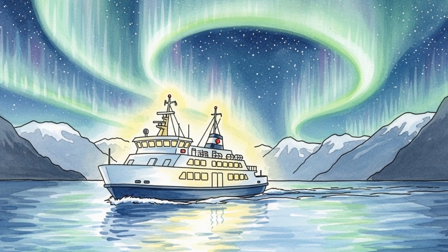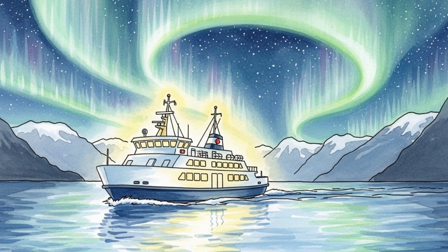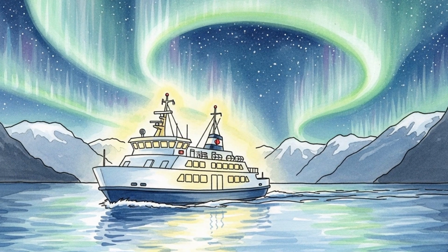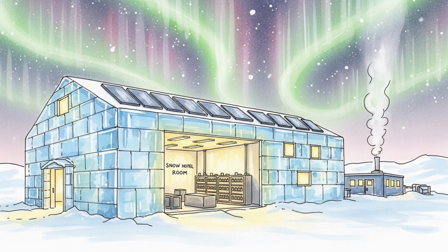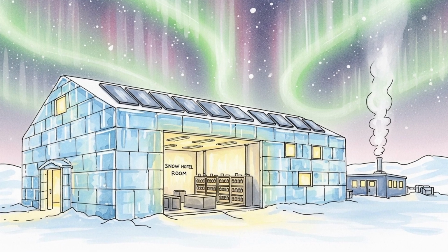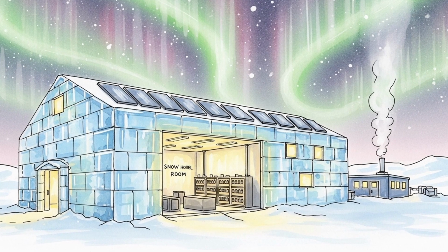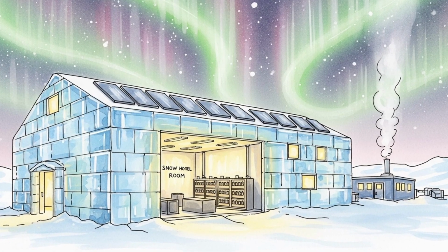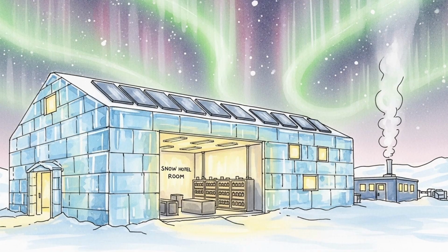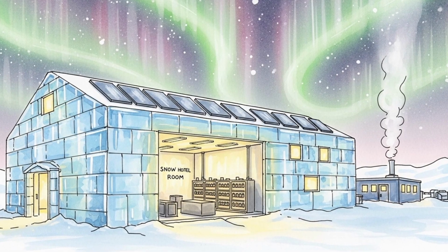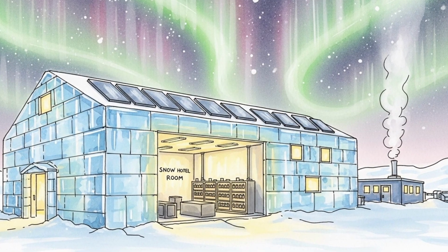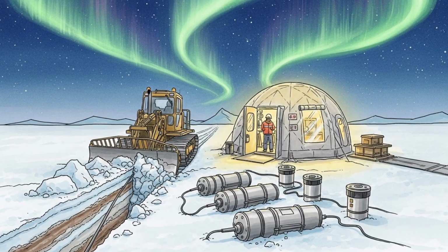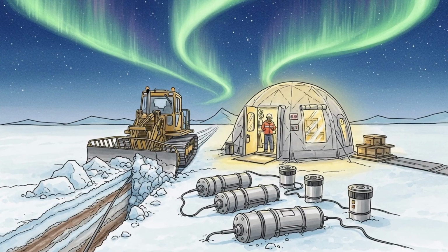Extreme scenario with widespread outages and long recovery. A very fast ejection arrives in less than a day. Southward BZ is strong and sustained. dB/dt spikes occur over large regions with conductive ground. Multiple extra high voltage transformers saturate. 2 or more units suffer thermal damage. Reactive power shortfalls cause voltage collapse in several areas. Islands form and black out. Black start plans are activated.